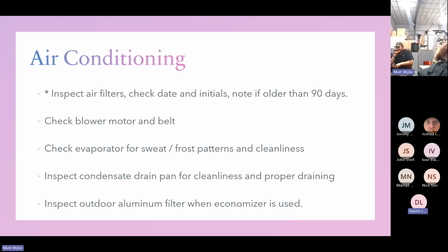So I'll always check motor speed. It's the same thing for heating mode. I'm sure you've all looked at some residential furnaces or rooftop units. A lot of the fan motors have a high speed and a low speed. Usually the low speed is for heating and the high speed is for cooling. If you're moving too much air through it, going full speed ahead while trying to heat, and your economizer is also letting 5% of the cold air in, you've got all these different factors.